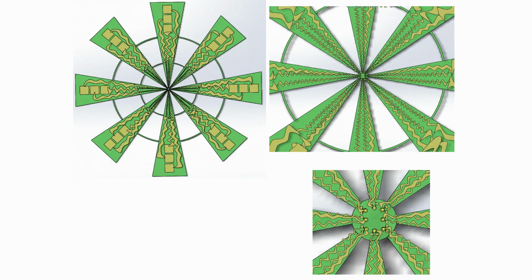So, like I said, for each strain gauge we require 2 contact pads, 1 and 2, and then on that there is an insulator on which there is an electrode, and that electrode consists of an SU8 pillar. So, this is a top view, it looks like this.